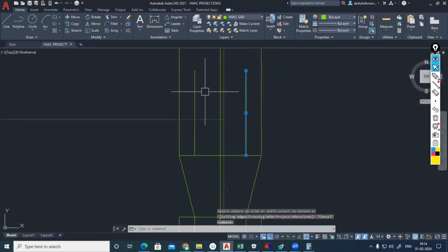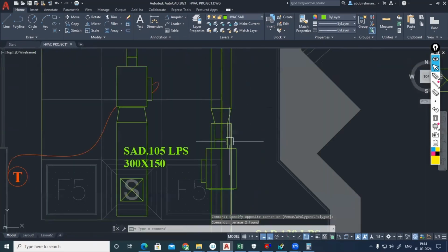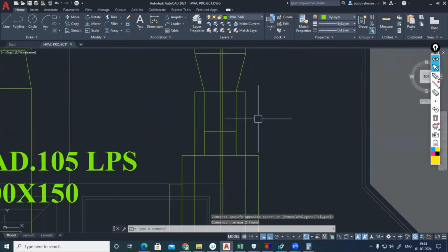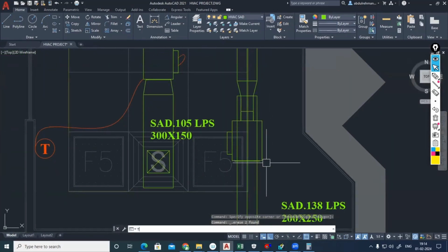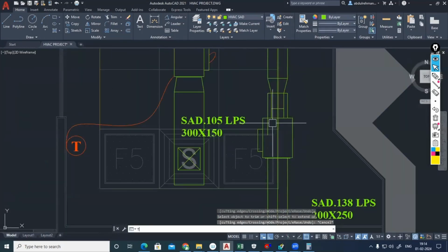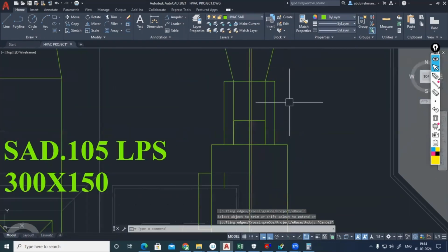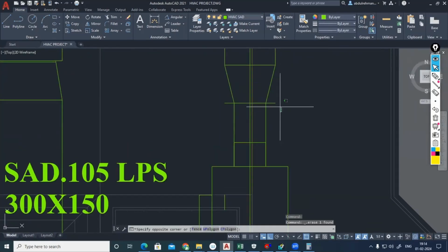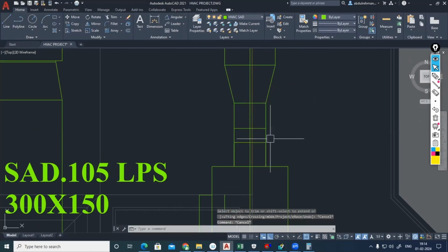Okay. Now after this we need a collar. We need a collar there. Trim this. From this point, the collar distance I need is 4 inches. Any distance higher than 4 inches is fine. Offset 100 mm enter. I'll be extending. Now there we can connect the VAV. But even if you are moving the VAV beyond that, that is fine.